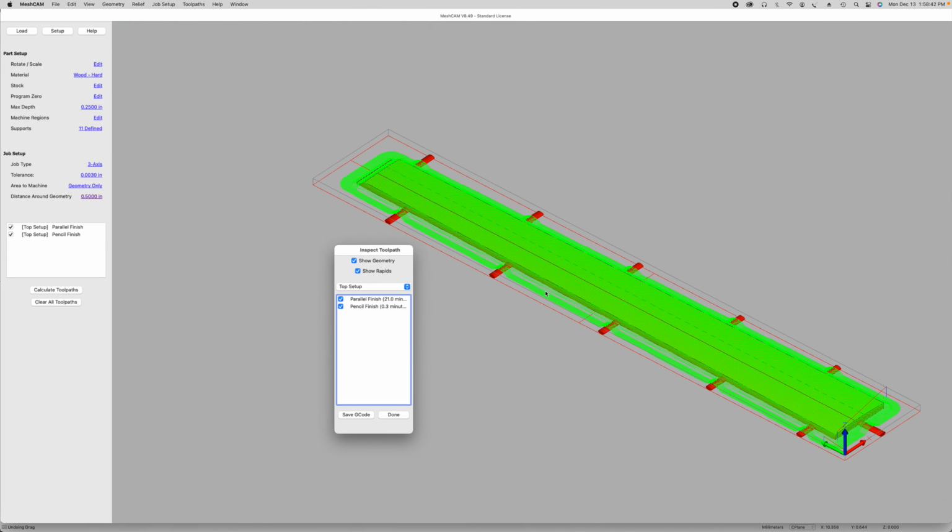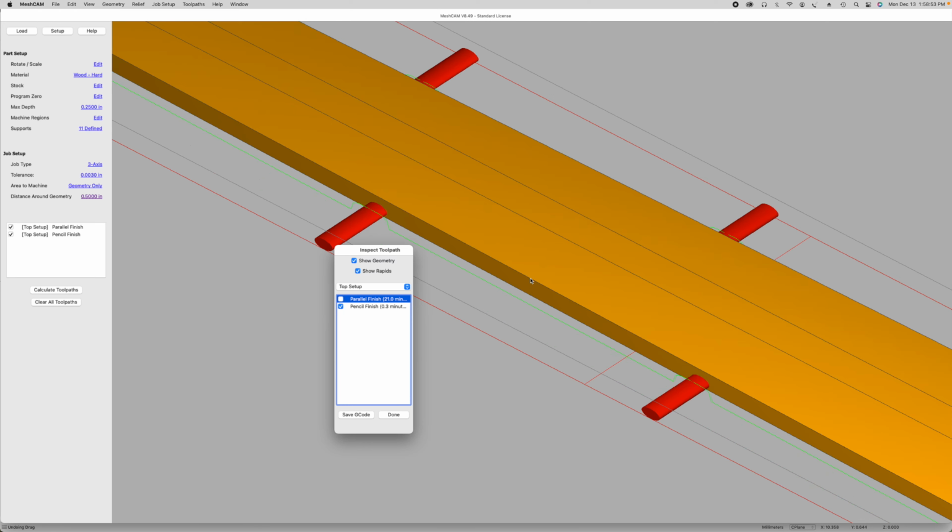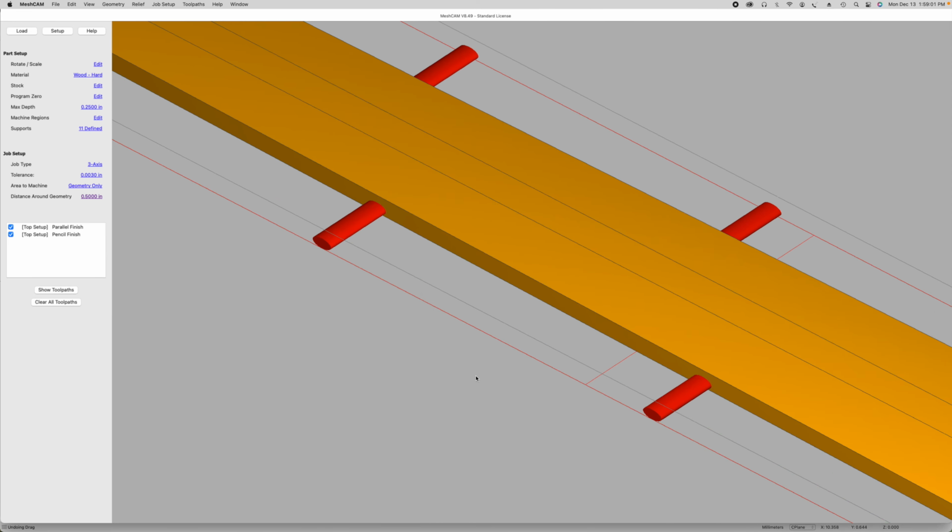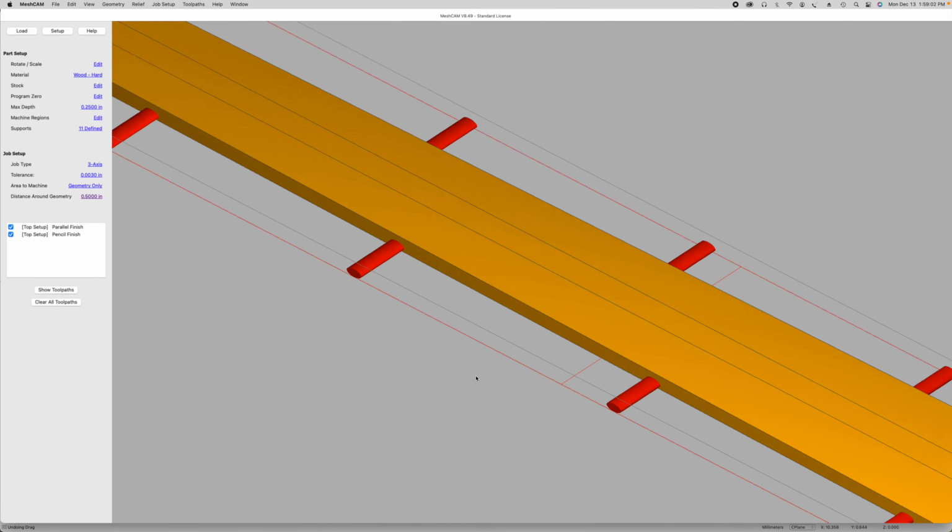And since this is a 1/2 inch round nose bit, what's going to end up happening is that edge, instead of being straight up and down vertical, is just going to curve out like the bottom of a swimming pool. And we don't want that at all. So what I have to do is trick MeshCam into carving just the top surface of the fretboard radius. And the way I've found to do that is if you look over here on the